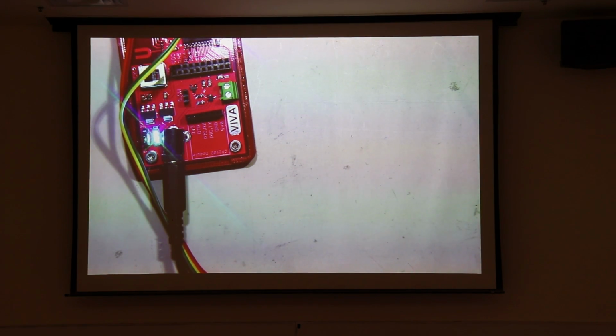You should put that in your brain and remember it. The way open collector works, the transistors driving the lines are set up like this, and it's usually pulled low, so it's going to be an NPN. Here's the base.